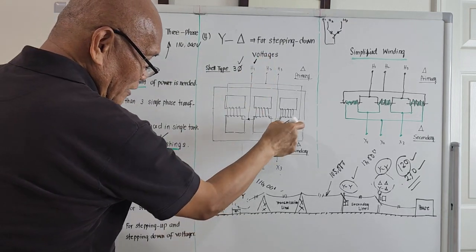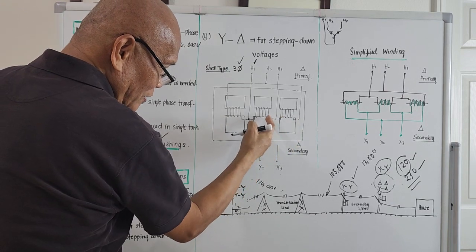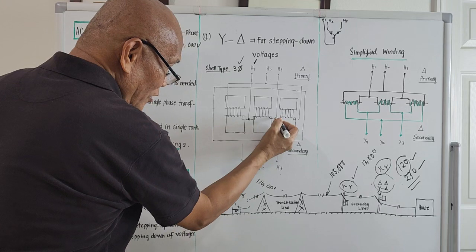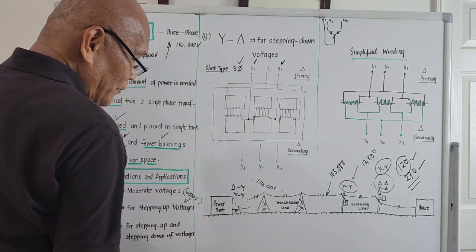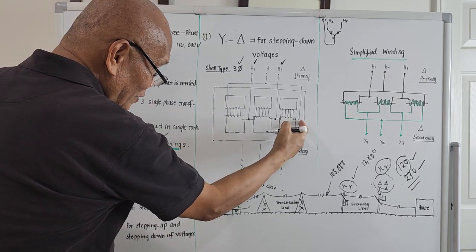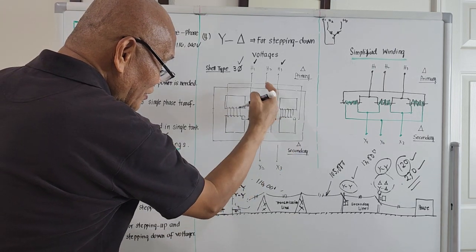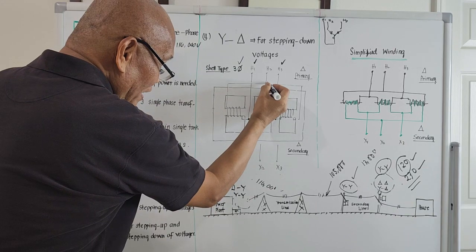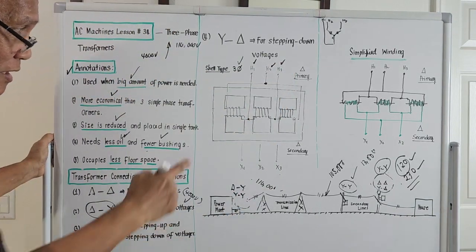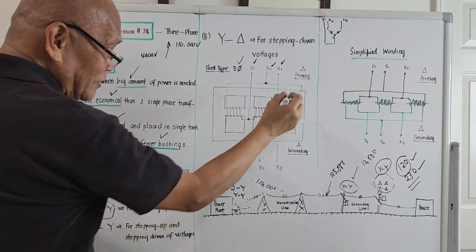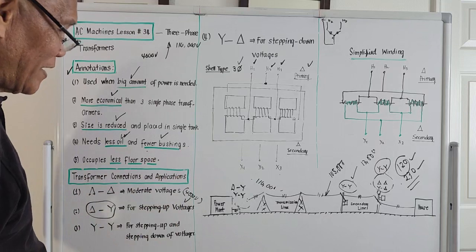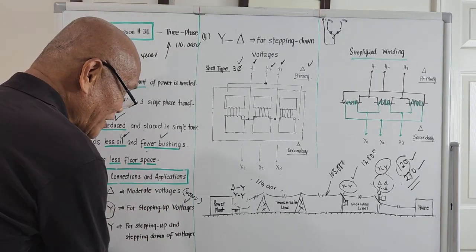Okay, another phase winding, we get the center tap. This one is connected with this, and the connection is here. We bring that one out, that will be H3. And if we connect the end of this one with respect to the end of this one, we bring it out, and that will be H2. The connection for this is delta, right? That's the primary. That's why I didn't place the secondary yet.